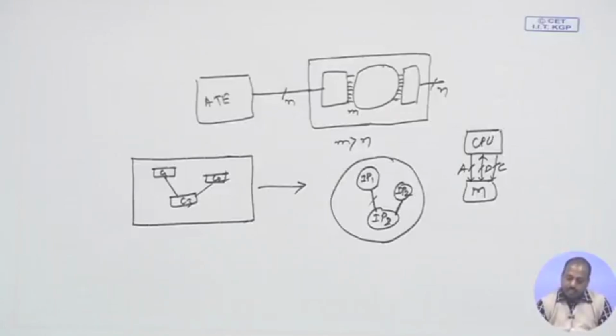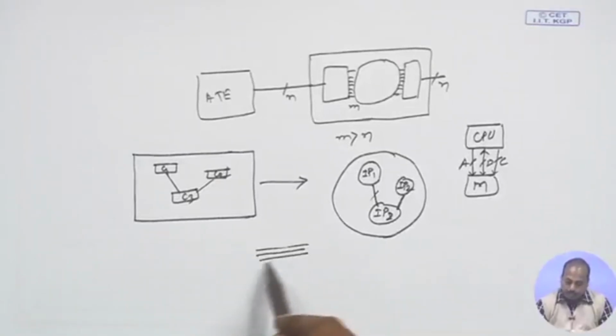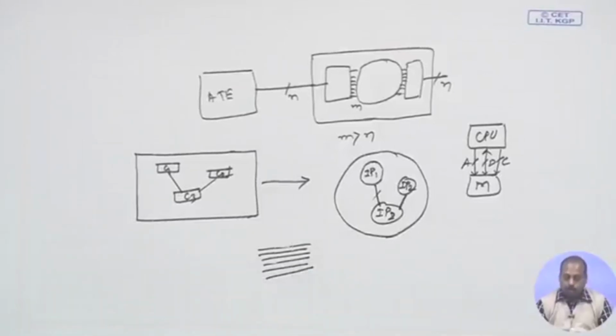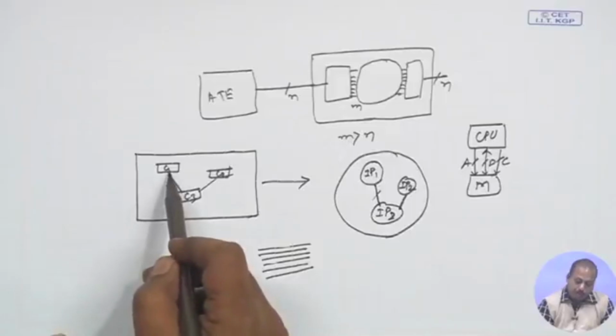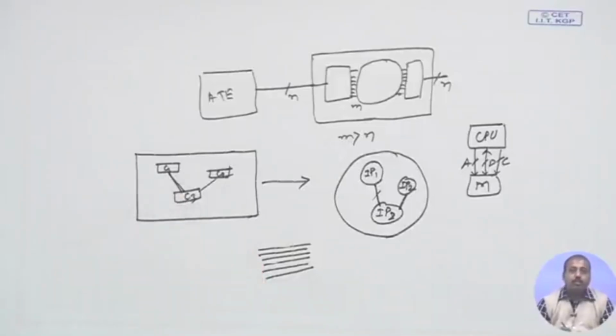Now, when there are a large number of lines running parallelly, we have the problem of crosstalk, the problem of interference between the lines. On the board level we had this problem, but it was not that much of an issue, because the system was operating at a much lower frequency. The delay of these external channels was deciding the delay of the communication, the frequency of the entire board.